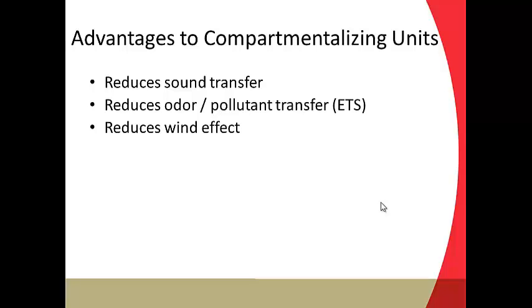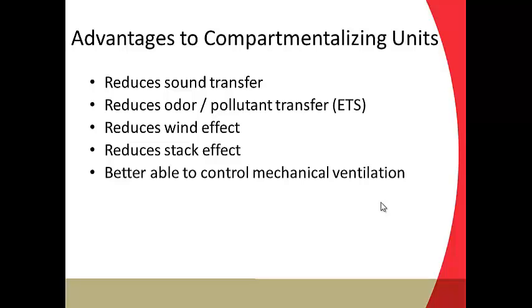And by compartmentalizing, you can greatly reduce that wind effect. And stack effect the same way. If you do a good job of air sealing between floors to compartmentalize that space, it reduces the amount of air leakage due to stack effect.